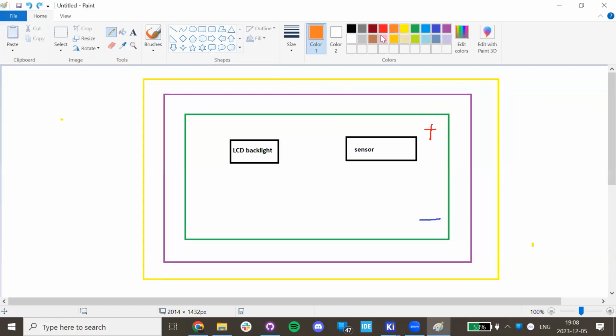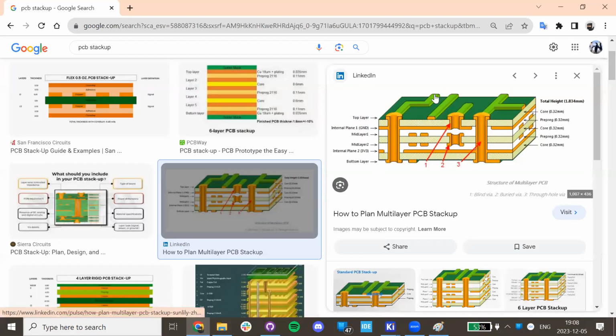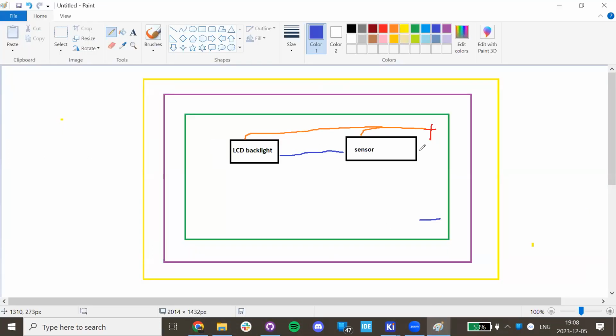Well, you could, of course, for every component, give it power, like this, and ground, right? You could route it as a trace, just as we cut out copper here. So either you make this whole plane ground or you cut out a trace. So why do we do it for the whole plane for the ground? Well, that is just for signal integrity purposes. So we've talked a lot about EMI. If you have a large shielded plane that can absorb EMI, but also think of these wires as having an